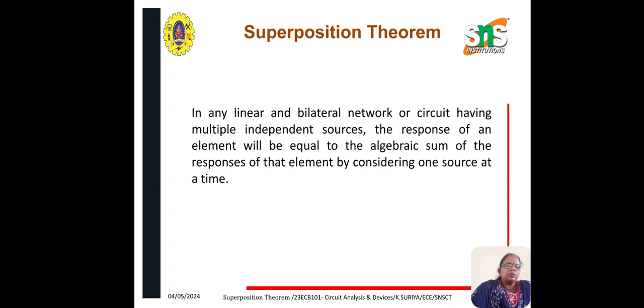Superposition theorem is used in electrical circuit analysis, which indicates that in a linear network any one branch of voltage and current can be found by inspecting the effect of the independent source respectively. The superposition theorem only applies to linear circuits in which the relationship between voltage and current is constant and does not include nonlinear components such as diodes or transistors. It can significantly simplify the analysis of complex circuits, especially when there are many independent sources.